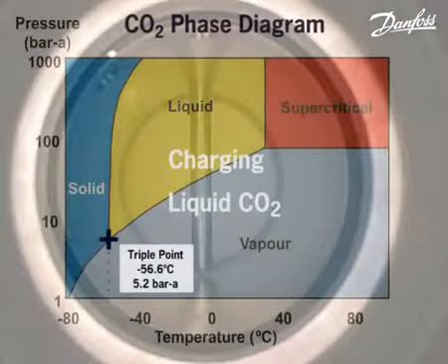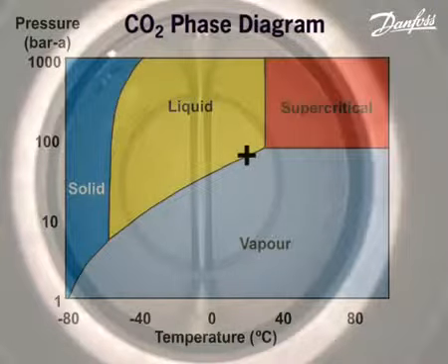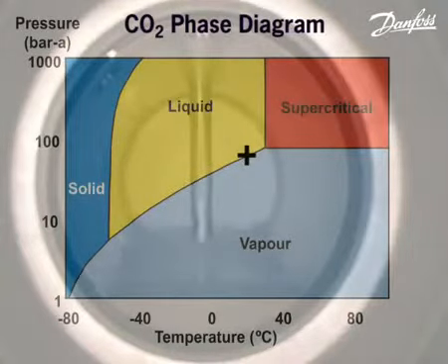We would now like to define the triple point, and in the first sequence the CO2 is cooled by forced evaporation to the stage where it passes through the triple point. The cell is charged with liquid CO2 at an ambient temperature of 20 degrees C, which has an equivalent pressure of 57.2 bar absolute.